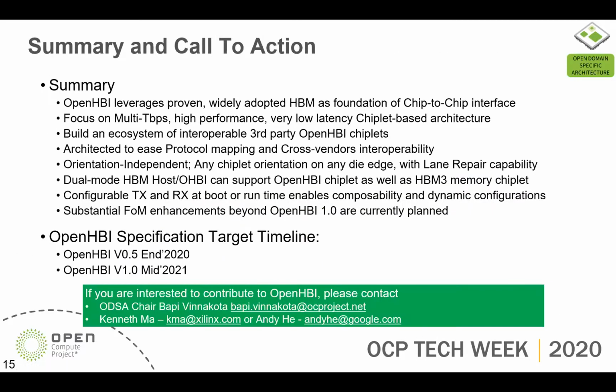So this is my last slide, summary and call to action. OpenHBI leverages a proven, widely adopted HBM as a foundation of the chip-to-chip interface. Our focus is on high-performance multi-terabit per second applications with very low latency in mind. The goal is to build an ecosystem that aligns with the ODSA's goal of interoperable third-party OpenHBI chiplets. So we architected the whole thing with a layered architecture to ease the protocol mapping and several additional rules for